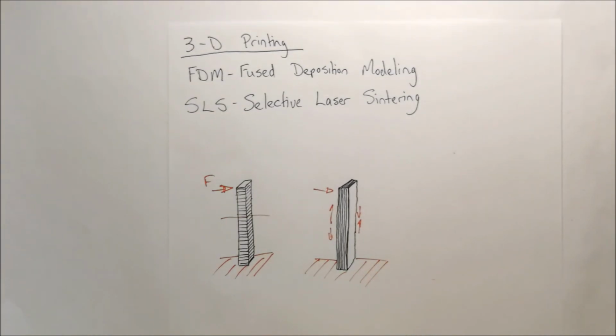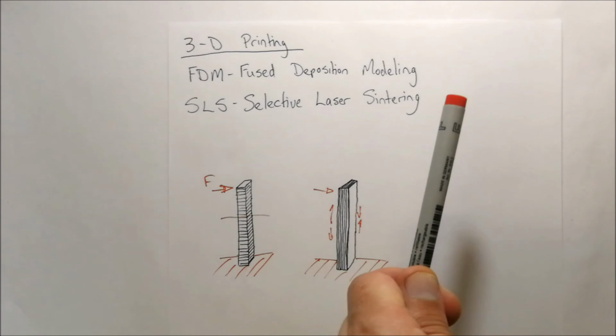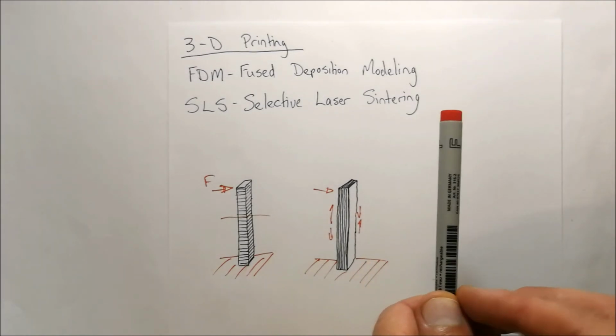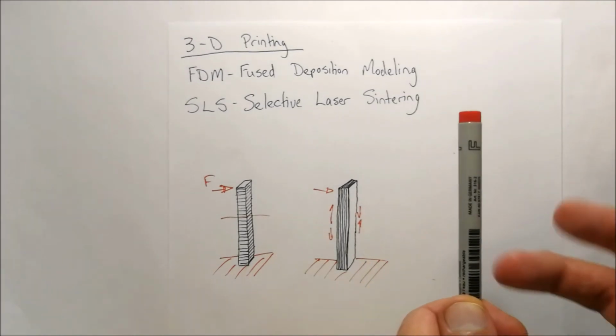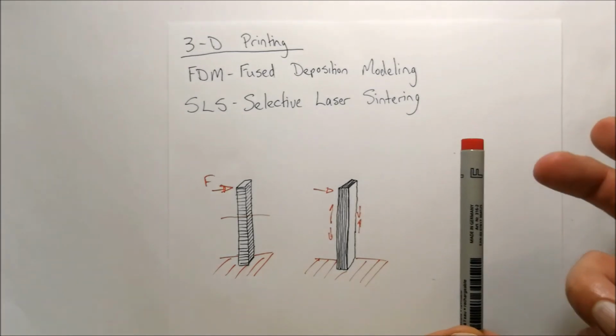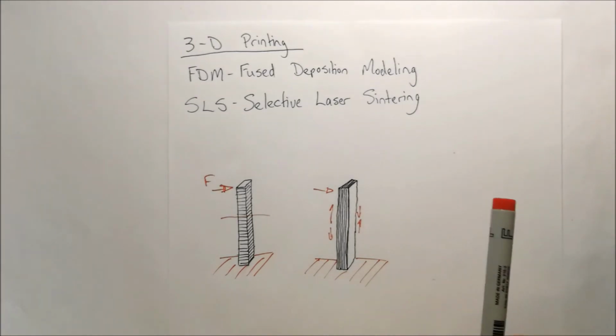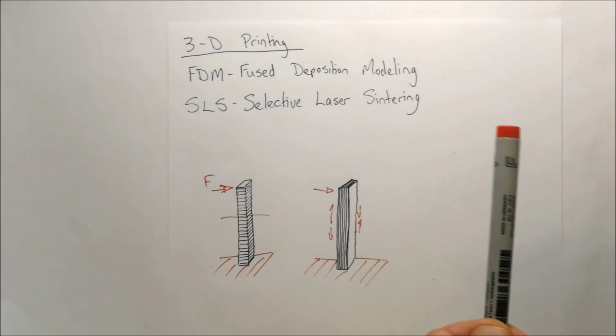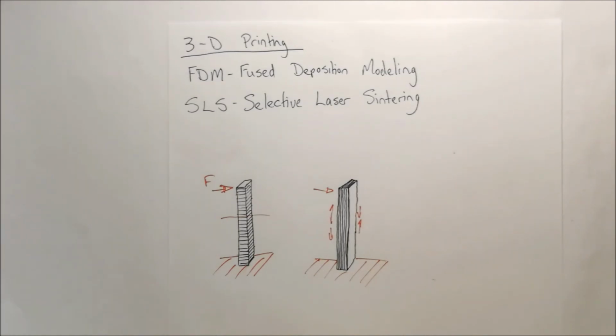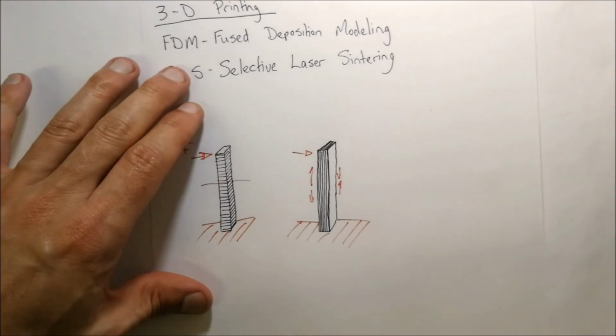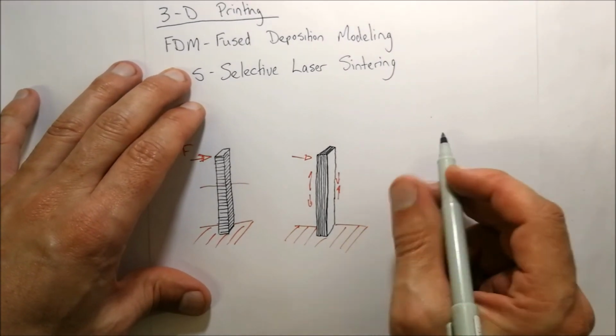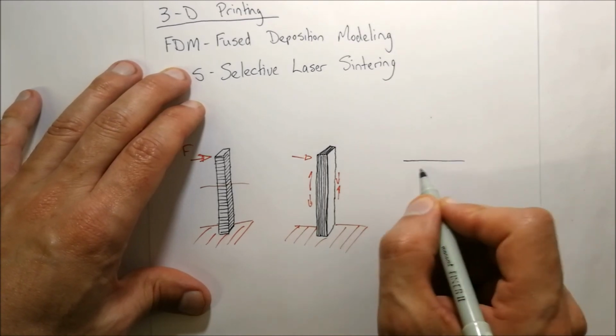If it is going to be something like a plastic cylinder, for example this pen, you might find that it's going to be easier just to machine it. With a plastic rod, drill a hole in the center of it and machine it to the specific thickness that you want. Also keep in mind that when you 3D print, and we're looking specifically now at this tube of this pen that we looked at, there often needs to be supporting material. So if you're wanting to print a tube,